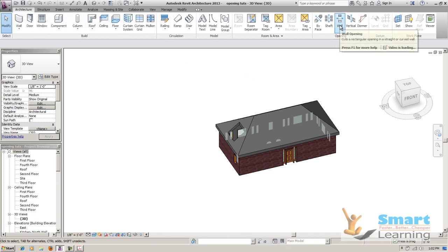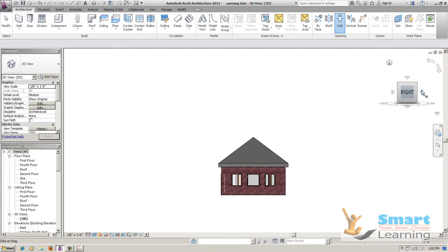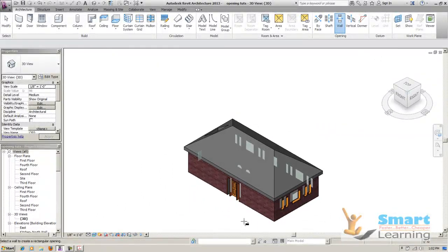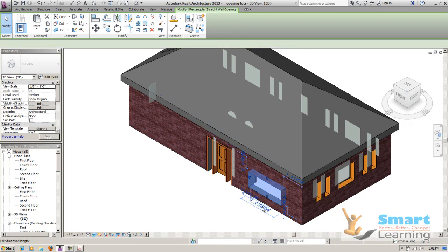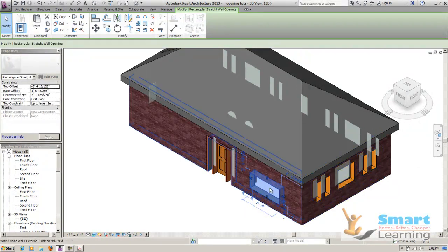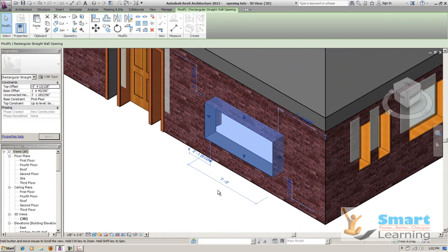Just like that, you can do it over the walls. If you have your walls, there you can have an opening. So I'll go to the typical views and I can control it. If you want to select a particular wall, first you need to navigate to the proper views and you can create your wall cut out. You can see from all the different sides where you need to have the opening. So this side I need to create the opening. So go to the wall and select the wall. Then you can create the opening dimensions here, whatever dimensions you need. When you select this, you can see the typical dimensions here. And what about the opening? That also you can set, the window sill. If you want to create an opening, you can also specify based on where you need to align it, etc.